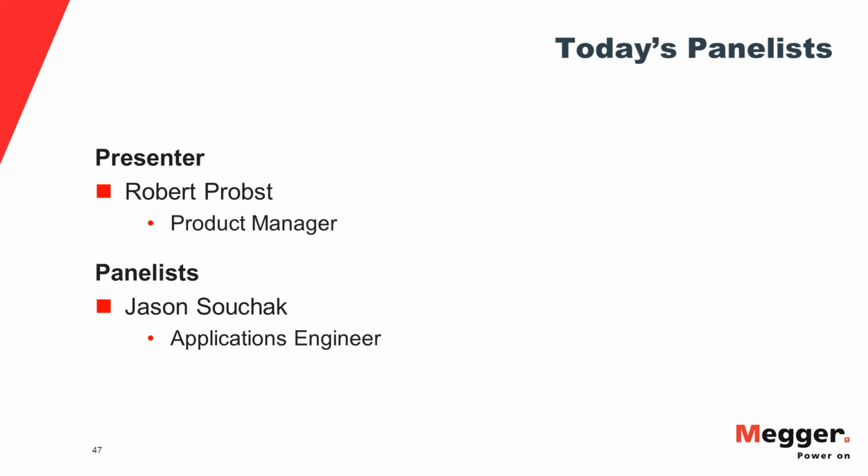Yeah, I mean, the question is interesting because everybody asks this, and I think the proper answer is, it depends, typical engineer's answer, right? It really depends on what you want to do, because monitoring is something completely different than trying to do condition assessment. Monitoring is not there to do condition assessment. It's just establishing a baseline, and you're looking for any changes, and then you have an emergency time frame that you can still act before something really severe is happening.